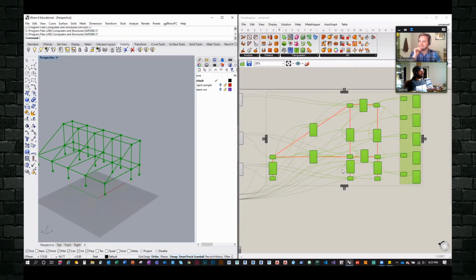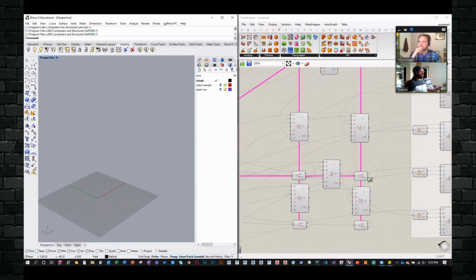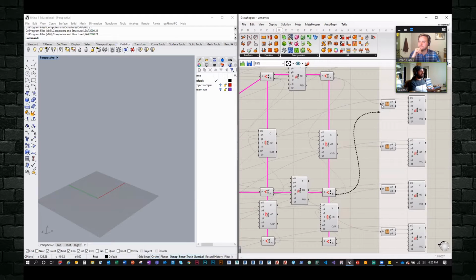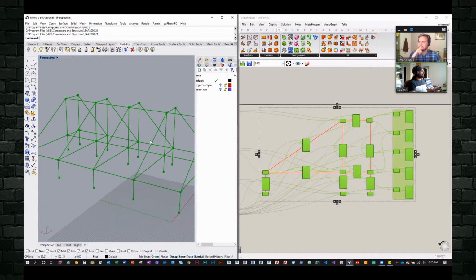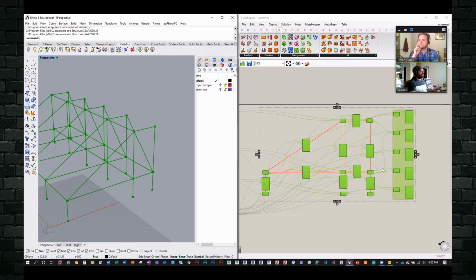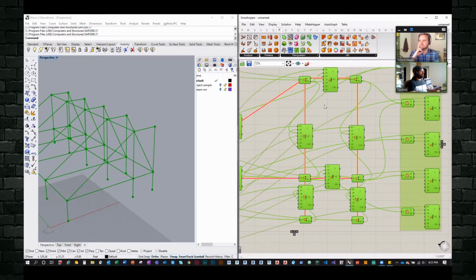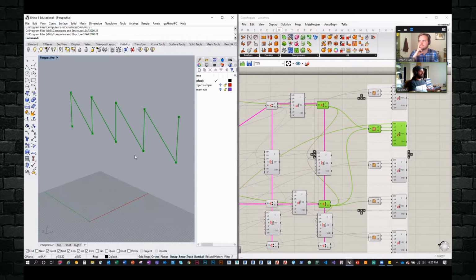So I just baked my frame in from Rhino to Grasshopper and laid it out so that now, like I said earlier, let's say I or one of my team members accidentally connected this and I'm visualizing this, well, I know that there's some sort of problem there, right? And so I know that the problem is at that point and that point, so I can quickly zoom in and say, this is where my problem is. And so these 2 nodes are connected to that, and that is connected to that, and there it is. That's how I kind of navigate through a script.